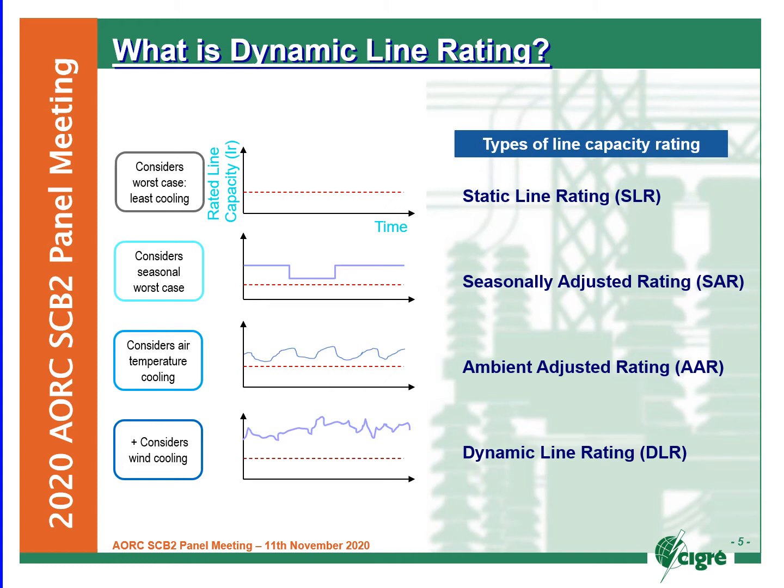This form of dynamic line rating is most interesting to access latent capacity from the grid because very small winds, like below 4 meters per second, already give more than 50% extra capacity, while a 2 degrees Celsius cooler ambient temperature gives only 2%. This means that especially in hot climates, the true dynamic line rating is what should be used to assess when extra capacity is safe to use.